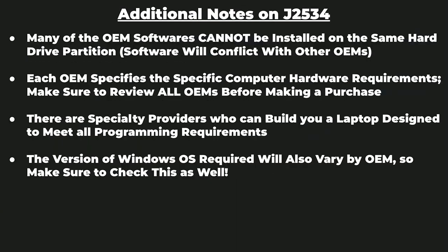Here's just a couple more notes on J2534. Again, it's really important to understand these points because when you are trying to do programming, you really want to make sure that you understand the limitations of the software itself as well as the computer you're installing the software onto. Many of the OEM softwares, including the J2534 softwares, cannot live on the same hard drive partition.